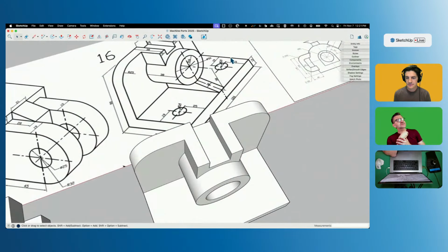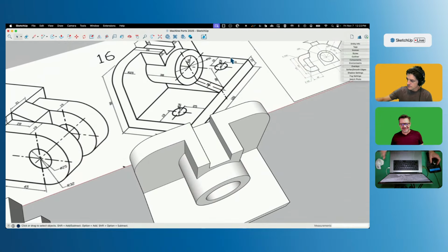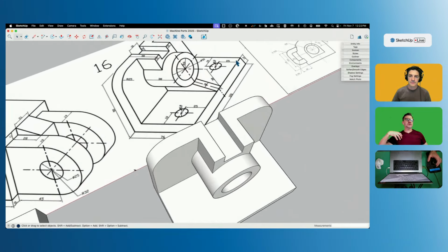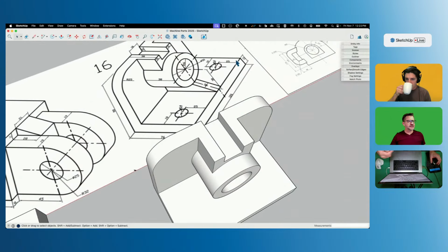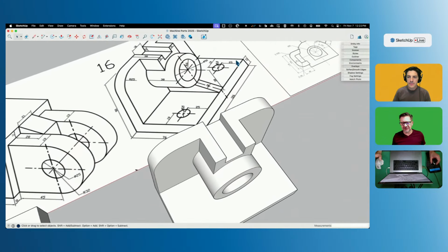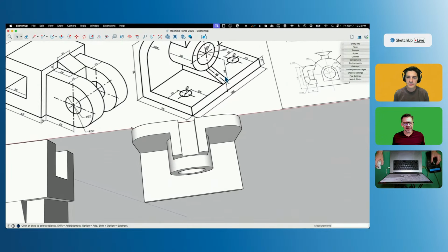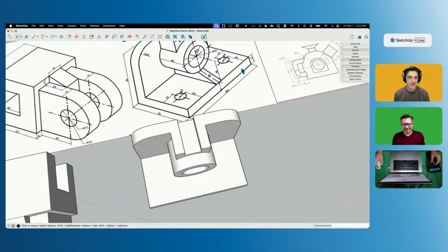Yeah, and it's one of the things we've talked about on here before: everybody models differently. They just do certain things that they've found help make things easier. For me, it's real quick to stay in the drawing mode and keep drawing stuff, and then come back with an eraser real quick and swipe at extra geometry. That makes more sense to me than spending a bunch of time creating, it takes me out of the flow to stop snapping, I guess. I've got to be clicking. Yeah, keep it loose and click away.